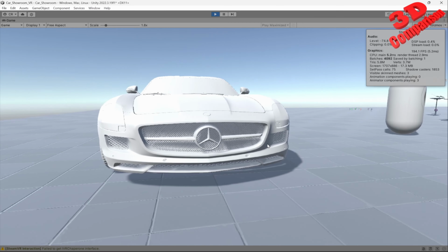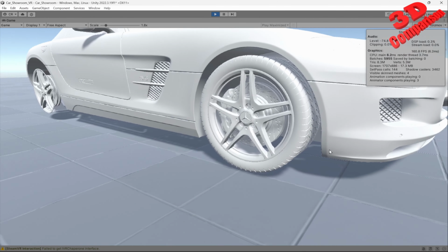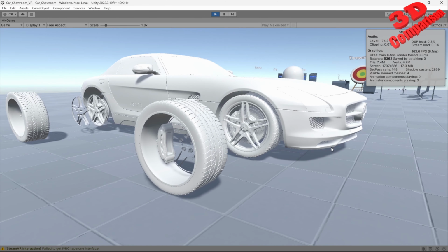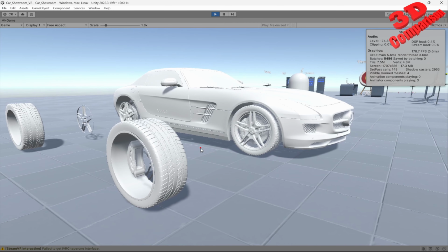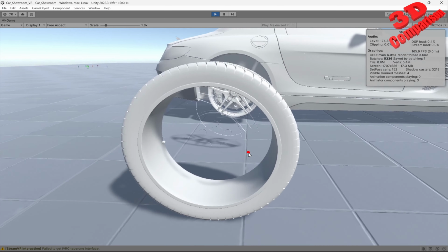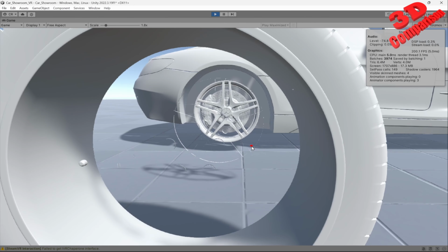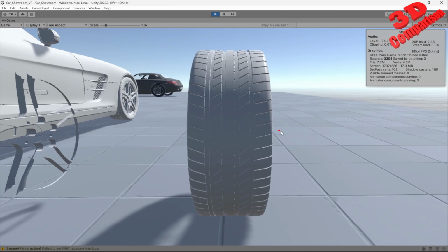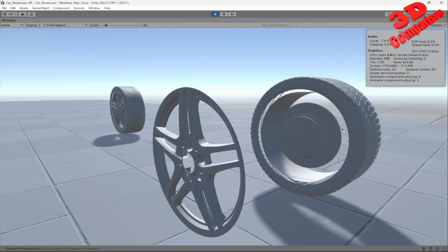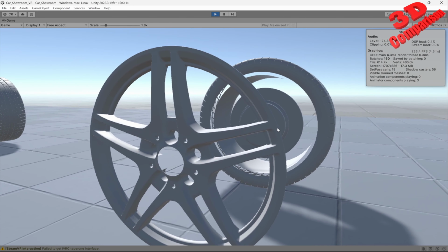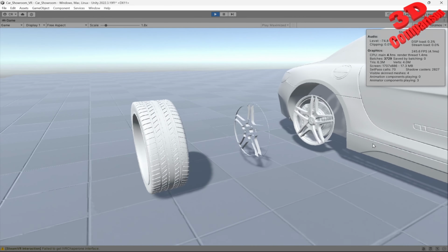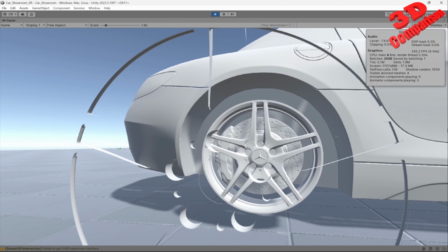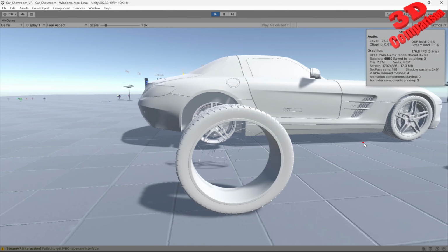But it is really important to make sure that the orientation is well defined within Blender. Because for example, we see over here that those on the left side will be translated over here to the right side. Also, there are many elements that are made without thickness, so they will only be visible from one side. For example, the car rim, if I take a look at it over here, we're going to see that the shading from the back will actually make it invisible in this case.